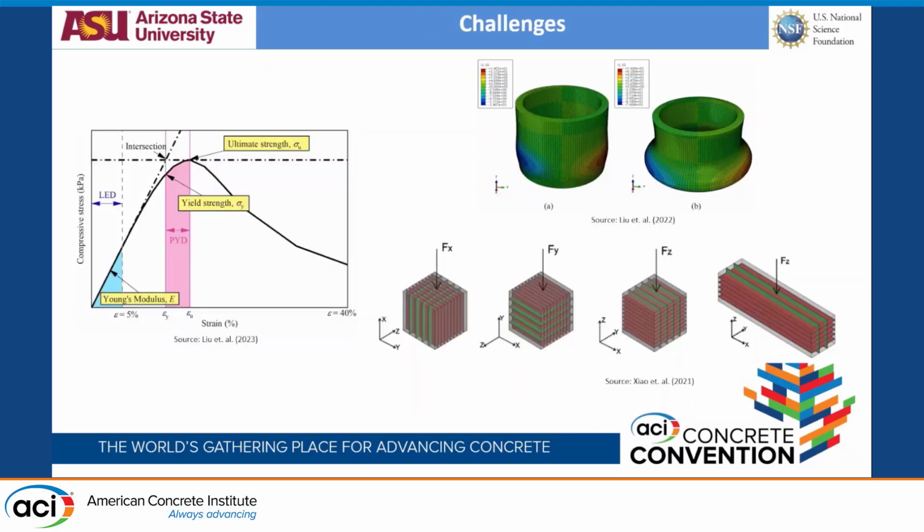printed elements. In modeling terms, there are a number of challenges in 3D printed elements, because in cast systems we have a more isotropic nature that we can model easily, while in 3D printed, how do you characterize the material that you have printed, how do you characterize it based on the overall versus a single filament, how do you check the deformation that you initiate during the printing, how do you incorporate the interfaces, how do you characterize those interfaces. So with all these challenges, there are different solutions people have put in front of others, and this is one of the solutions we came through.